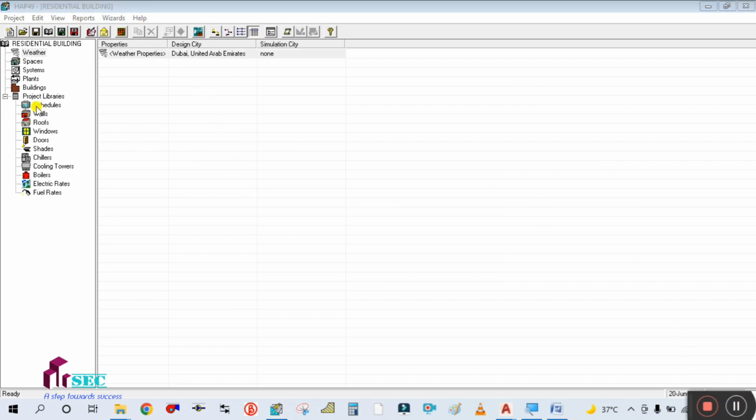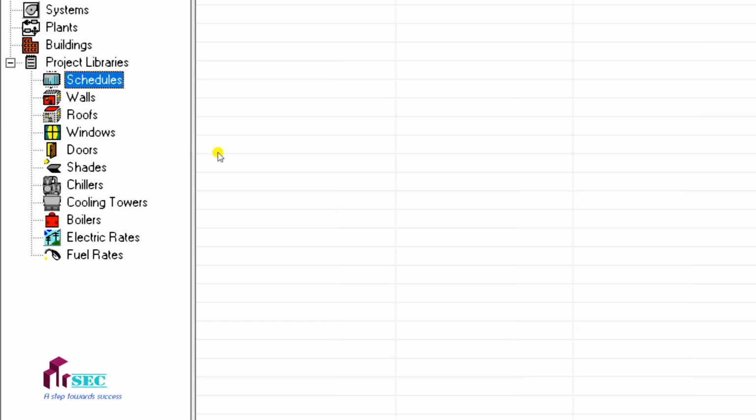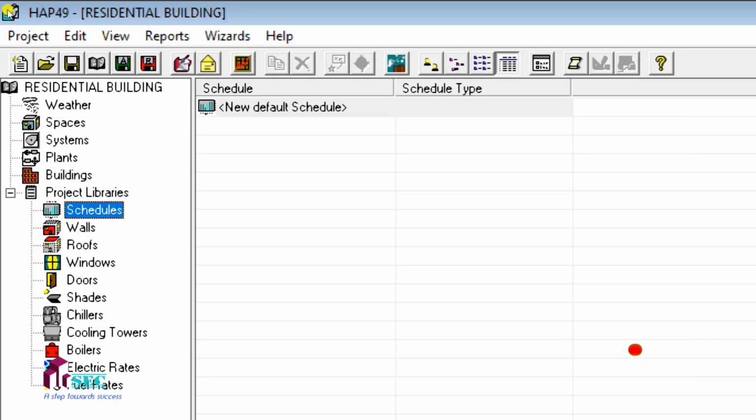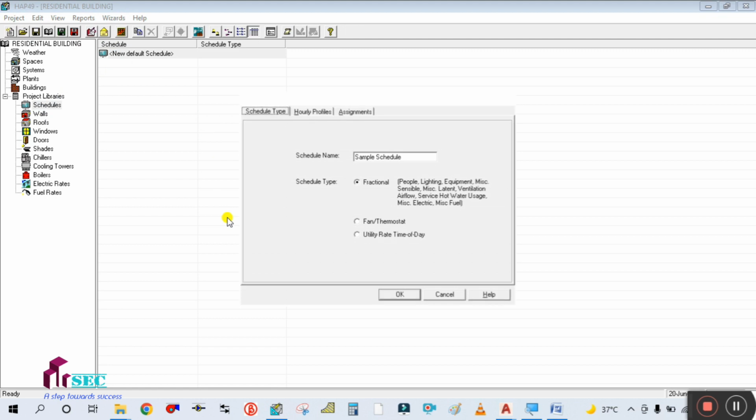Now create the schedule. So simply click here on schedule. Okay, single click on schedule, then double click here on new.